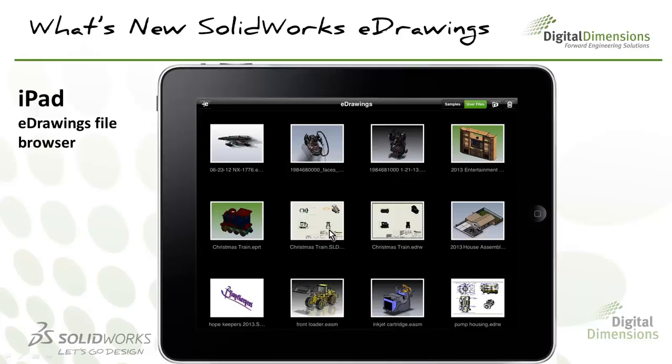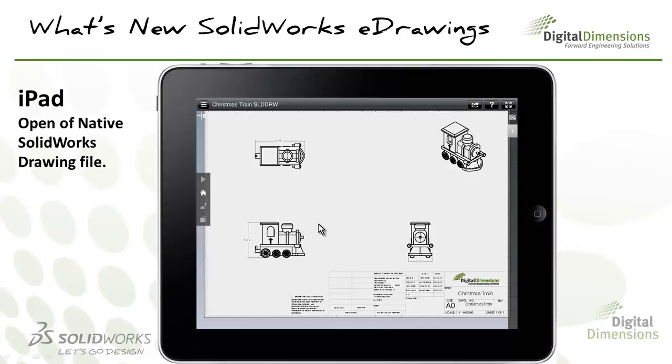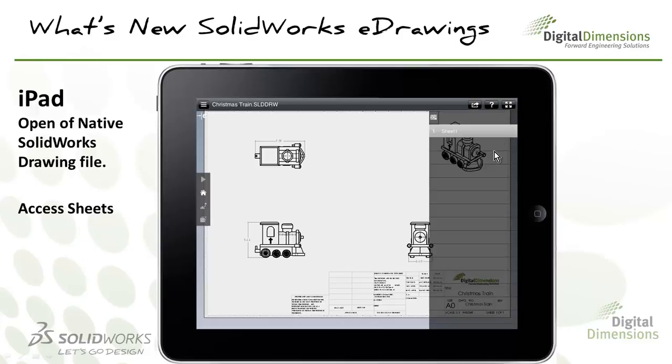And from my file browser, I'll go ahead and launch a native SolidWorks drawing. And if you happen to open a drawing with multiple sheets, in order to gain access to the additional sheets, simply click on this icon here, and then you could access them from here. My drawing only has one sheet, so I'll go ahead and open another file.